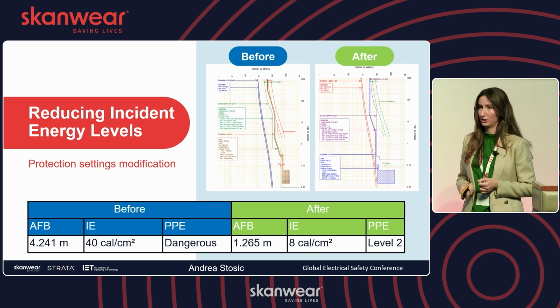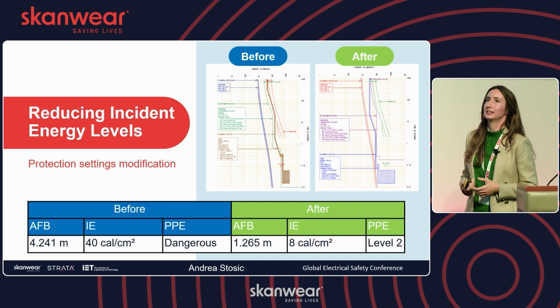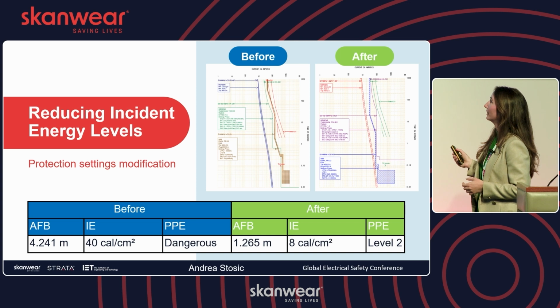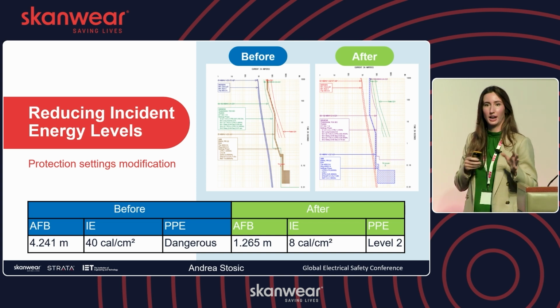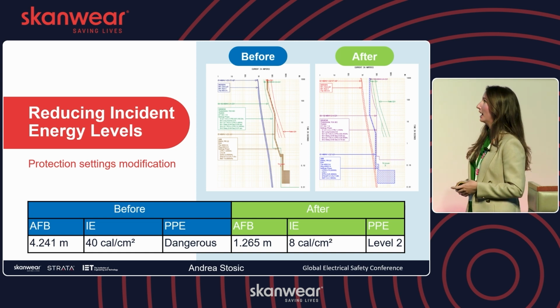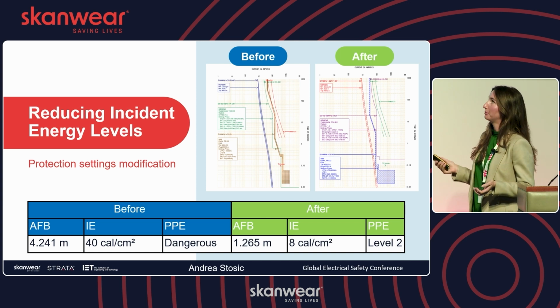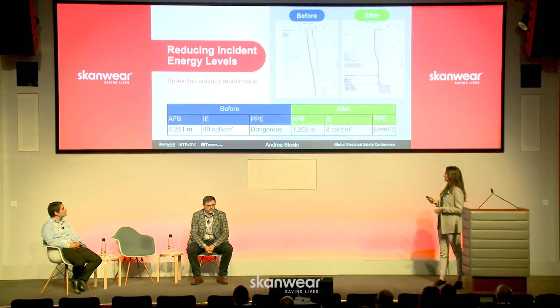On the next slide, I will show you how changing the protection settings can greatly impact the incident energy levels. And in this case, it was for the better, and it was a significant change as well. So here you have the before and the after situation, before using the existing settings that we had implemented on site before we started with the arc flash study. This is a time current characteristic graph.